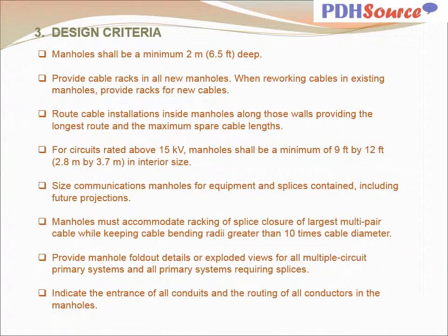Manholes must accommodate racking of splice closure of largest multi-pair cable while keeping cable bending radii greater than 10 times cable diameter. Provide manhole fold-out details or exploded views for all multiple circuit primary systems and all primary systems requiring splices. Indicate the entrance of all conduits and the routing of all conductors in the manholes.